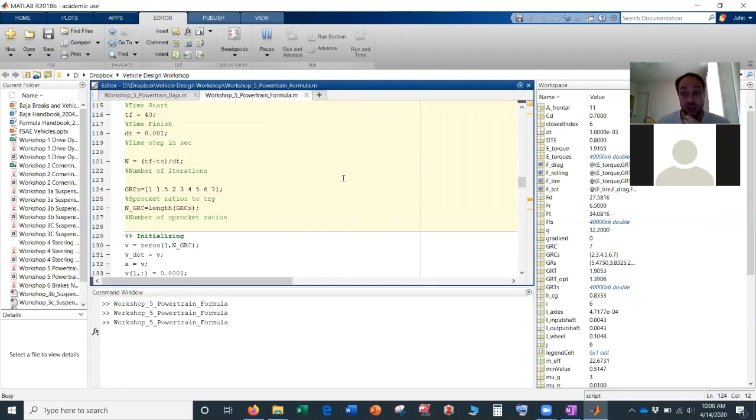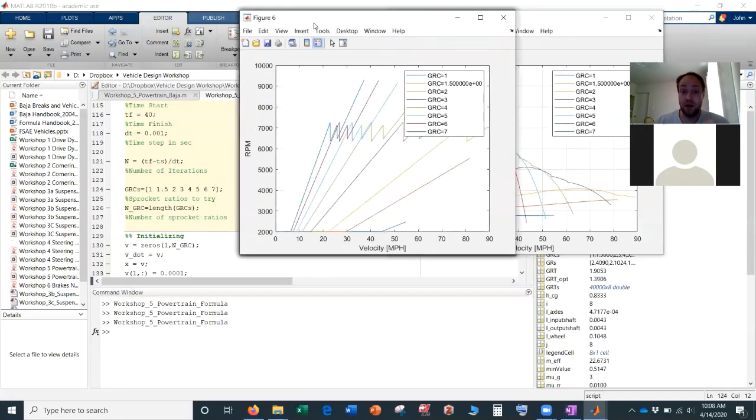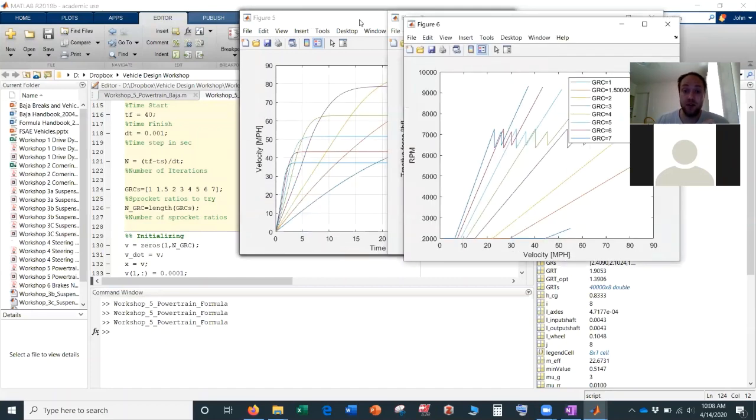Right, and so you see you can't talk about just the gear ratios inside the transmission without talking about what you pick as your sprocket, because that's really shifting the whole set that you pick left or right, basically, for the total gear ratio. So what's actually more important is how many gears you have and the spacing between those gears in terms of their gear ratios. If you're only going to use a certain number, that's what you should be caring about, not the actual absolute values.